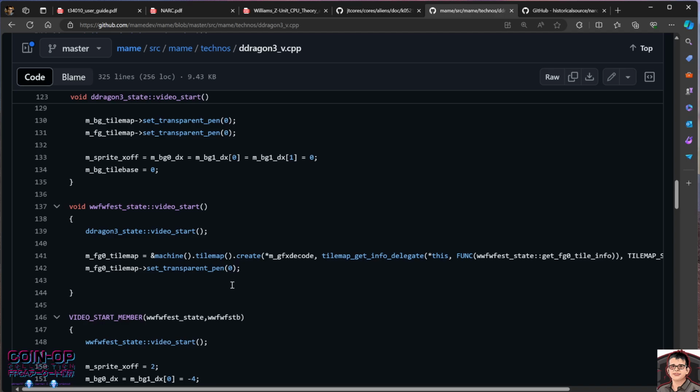So it goes from 8 to 248, right? So it's 320 by 240, right? And the vertical display height is 240, yes, but the line counter starts at 0 and goes all the way to something like 272 or something like that. But 240 of those lines are active lines, okay? And it starts from 8 and goes to 248.